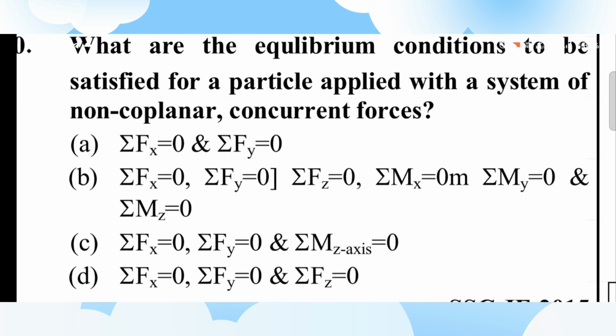Next question, what are the equilibrium conditions to be satisfied for a particle applied with a system of non-coplanar concurrent forces? A. Summation Fx equal to 0, summation Fy is 0. B. Summation Fx 0, Fy 0, Fz 0, Mx 0, My 0 and Mz 0. C. Summation Fx 0, Fy 0 and Mz 0. D. Summation Fx 0, Fy 0 and summation Fz 0.